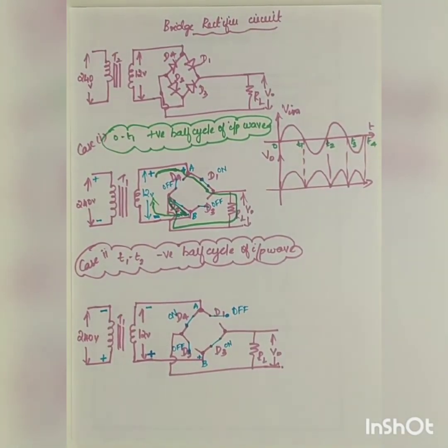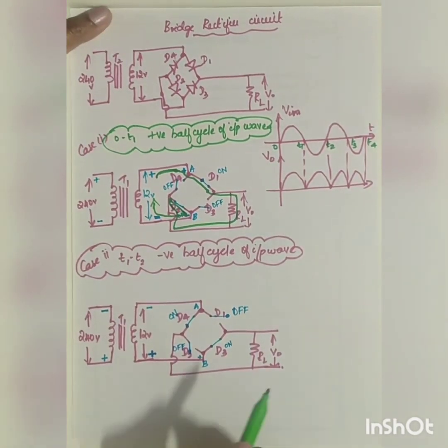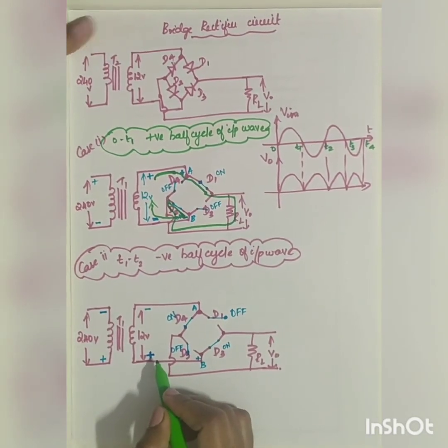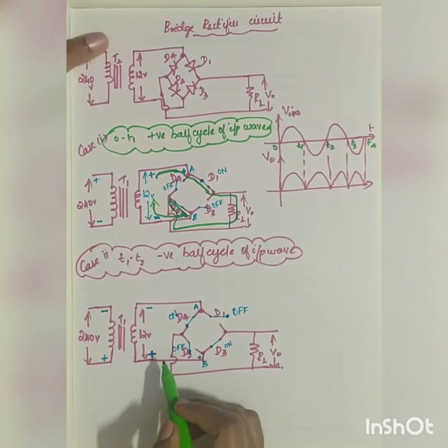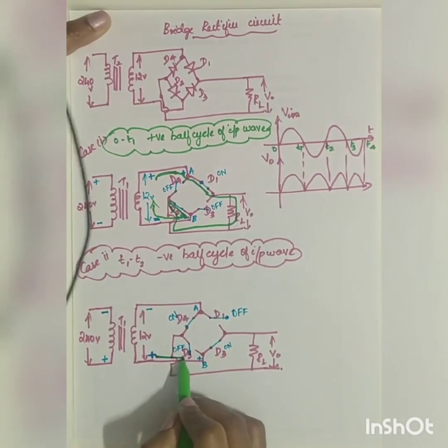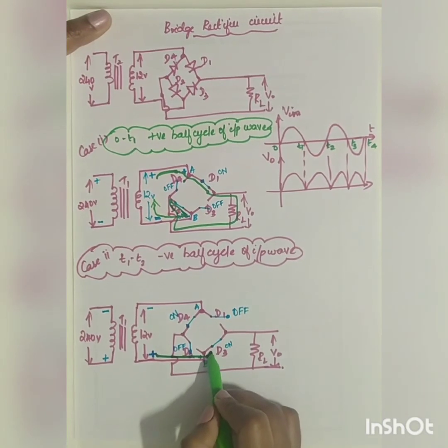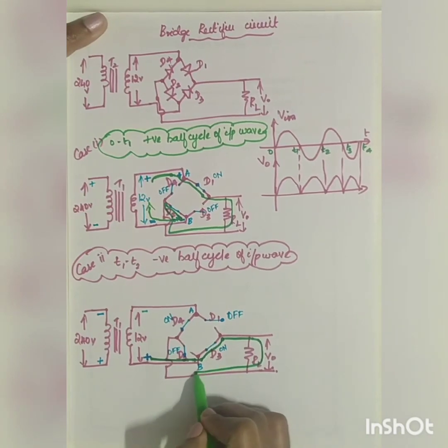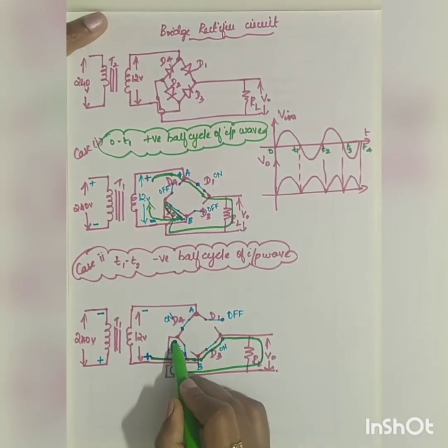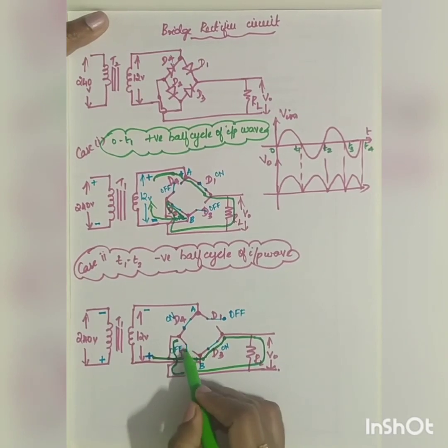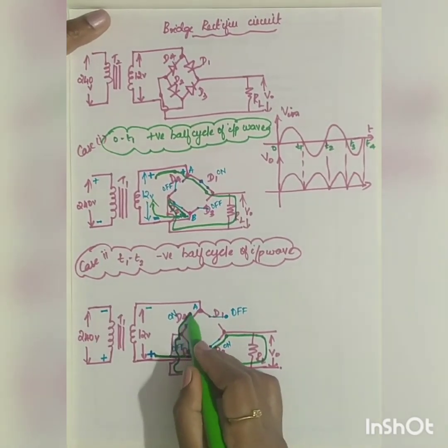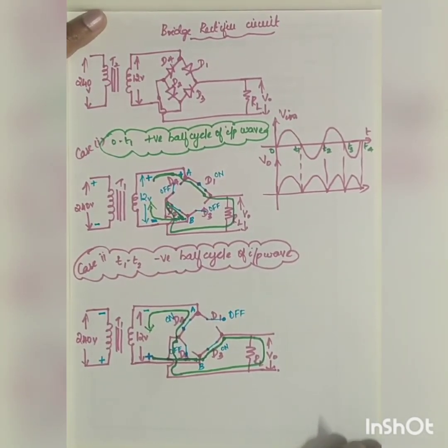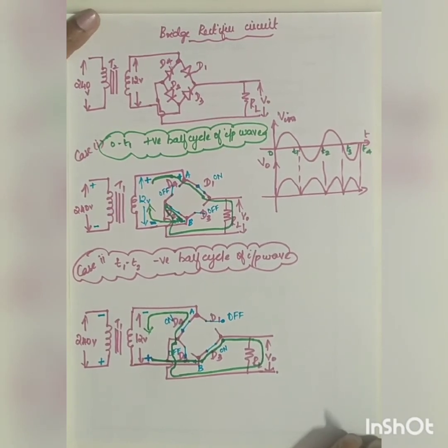Now can we see the direction of the current flow? So always the current flows from positive to negative. Now it starts flowing from positive through B, that is to D3. Again it comes back to RL. It sees the path. Here there is a path. It goes here. It sees two sides. D3 is open, so it goes along D4 and it reaches the negative. So this will be your current flow. Okay. So hope you would have understood all these three types of rectifiers.